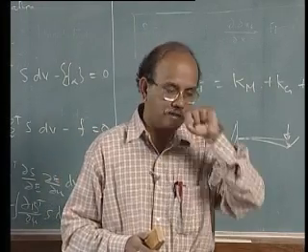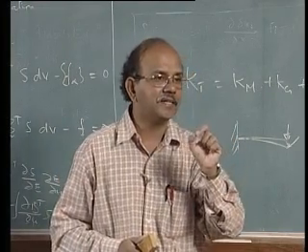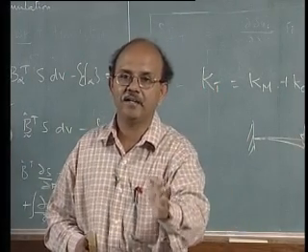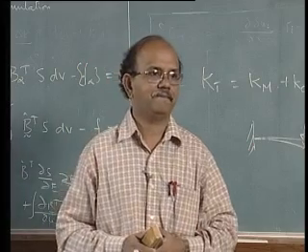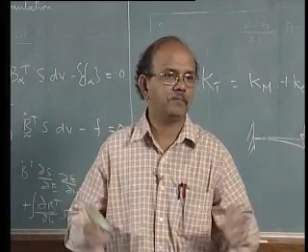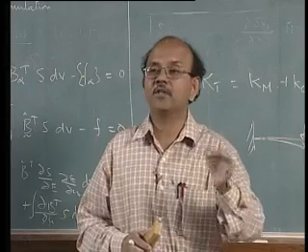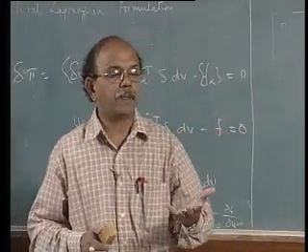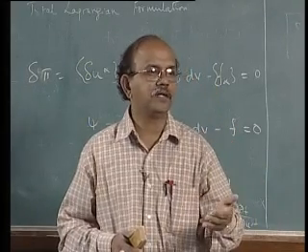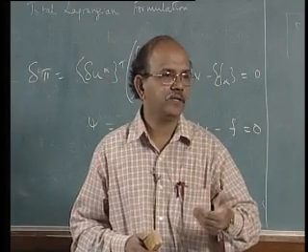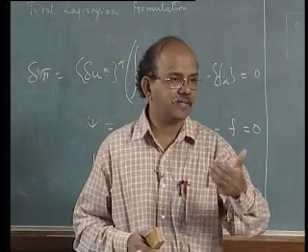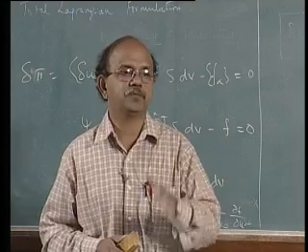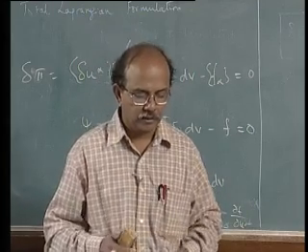Current coordinates are small i, but in this case it is actually not Eulerian, but the converged state at, say, Tn, time step n. This is what is called the current configuration. In other words, you update all the coordinates of the body to the current, or Tn, by adding to the coordinates the total displacements.